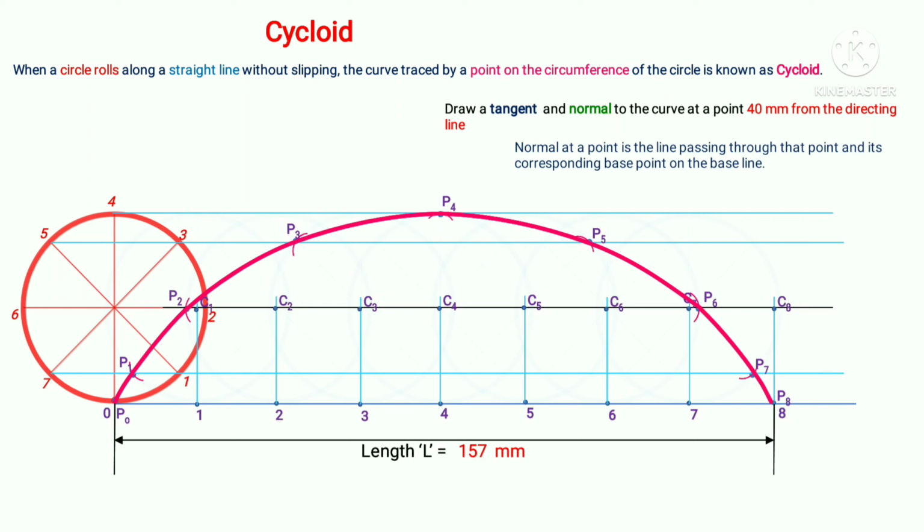If we draw another line passing through the point P3 but perpendicular to this normal, that line would be the tangent, and in this case it is the deep blue color line. And in this way we can first draw the normal, and then perpendicular to the normal passing through that point we can draw the tangent.